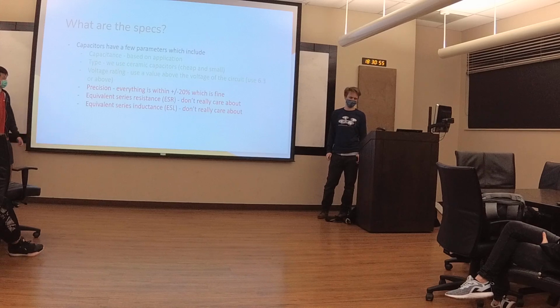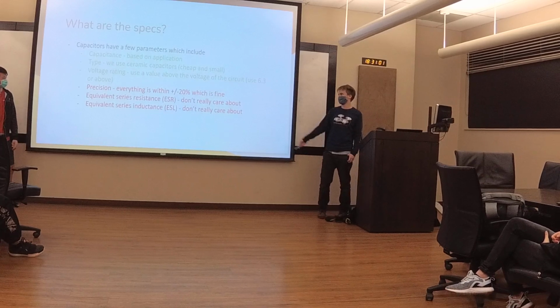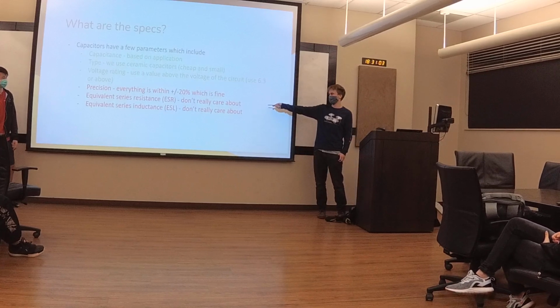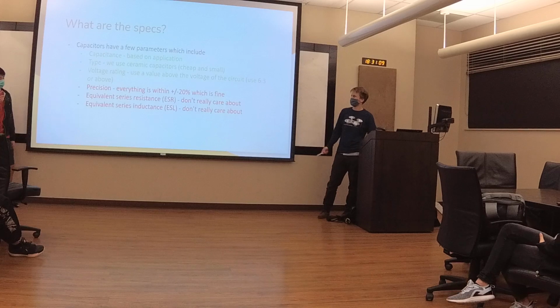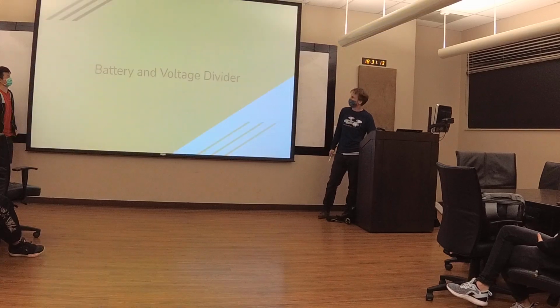So these ones in red you don't have to worry about. Precision we don't really care about. ESR we don't care about. ESL we also don't really care about because we're not working at very high frequencies. Package size and surface mount, yeah, we care about that.